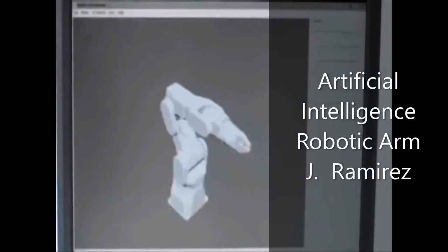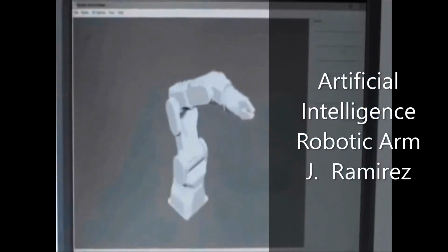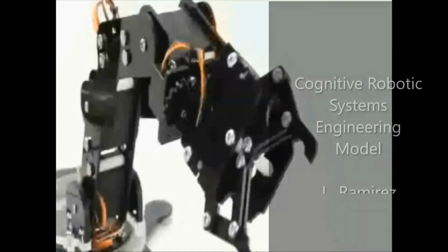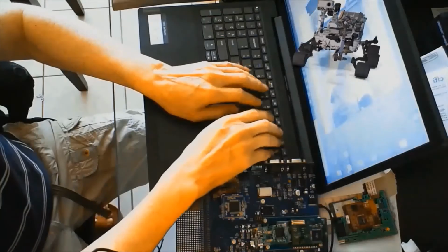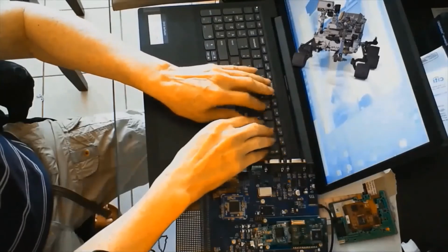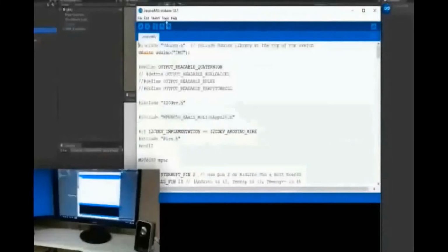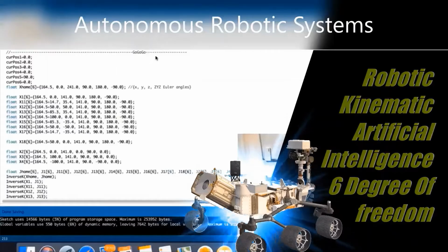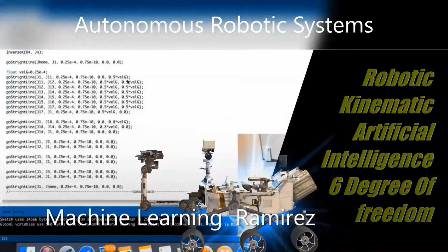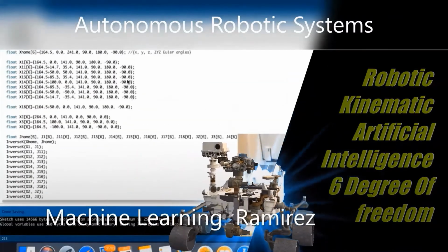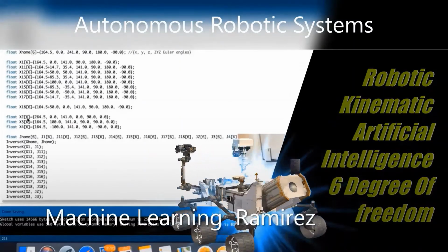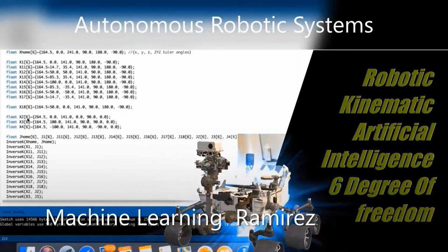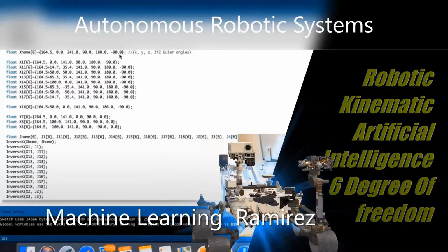The distance between the sensor and the empty sorting area is set to approximately 14 centimeters. If the measurement is lower than 14 centimeters, the sensor recognizes that an object is placed in the sorting area, and the robotic arm picks it up and puts it into a bucket.